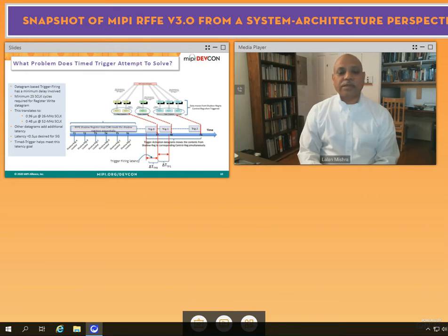But like I said, this 25 cycles itself is going to require some latency, which is shown here. And our goal in the 5G world is to be in the ballpark of half a microsecond or less to be more effective. But please keep in mind that this is precisely, or only, if you consider that you send the command sequence to load the register and then move from the shadow register. You also have to factor in other variables. For example, the bus may be occupied by other types of data transmission, which means that the bus is not always available to you, and therefore more latency could be added.